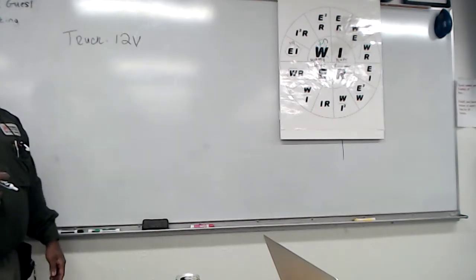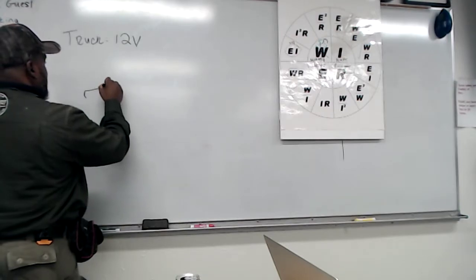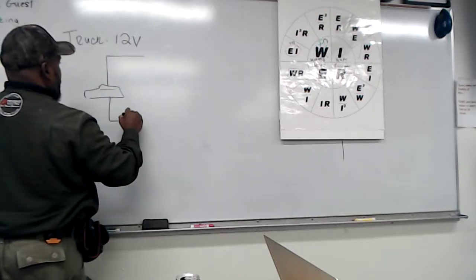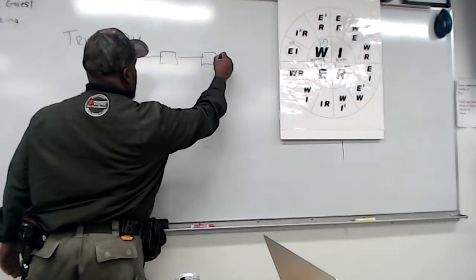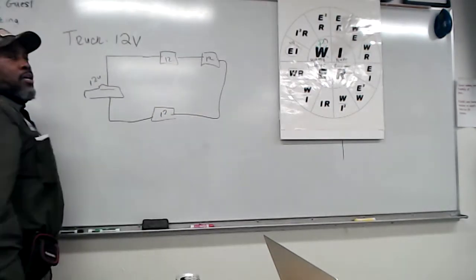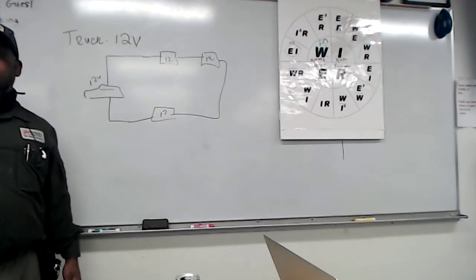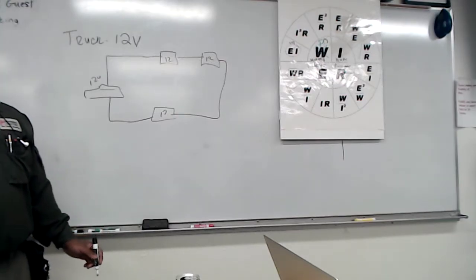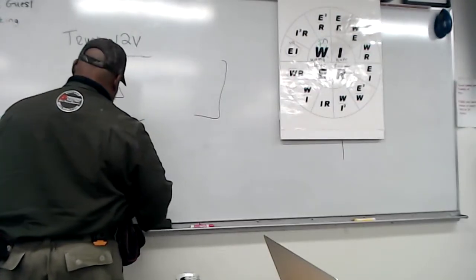Parallel circuit. Right? Why? So here's the truck, and I'm not a good drawer. Here's the truck. It has 12 volts. It needs 12 volts to work. If I put a battery here, and a battery here in series, how many volts are going to be on this truck? 36 volts. It's going to blow the battery out of that truck. It ain't going to work. So I can't put it in series. I came so close. So I got to put this in parallel.